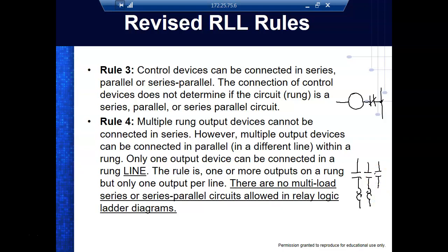So the problem we have with motors is when we start them, they draw about 6 to 8 times. So up here I might have a fuse. Let's say our motor to run it took 10 amps to run it.